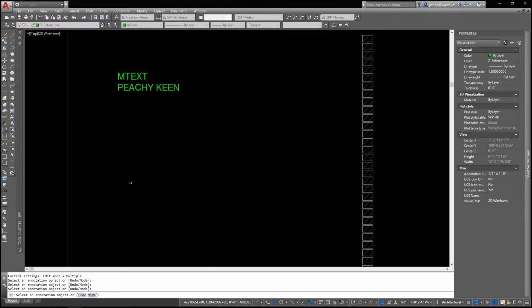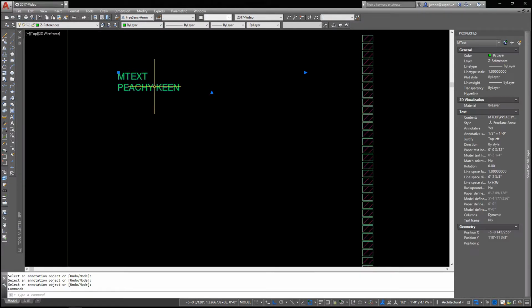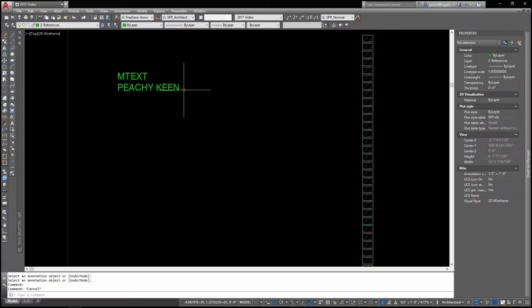If you ever want to set up a special title block that has some custom properties, that's one way you can do it. Of course, there's also the option of sheet sets, but like I said, not going to get into that quite yet. This is a nice step along the way, and there might be some other instances in which you might want to use some custom properties such as that, especially if you want to keep them hidden. And maybe just put them in a non-printing layer off to the side, information to share with other users, that kind of thing. Anyway, we've seen how to access those.